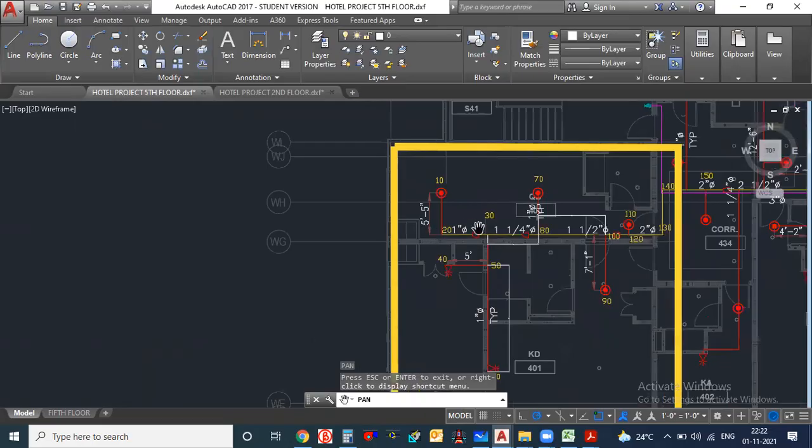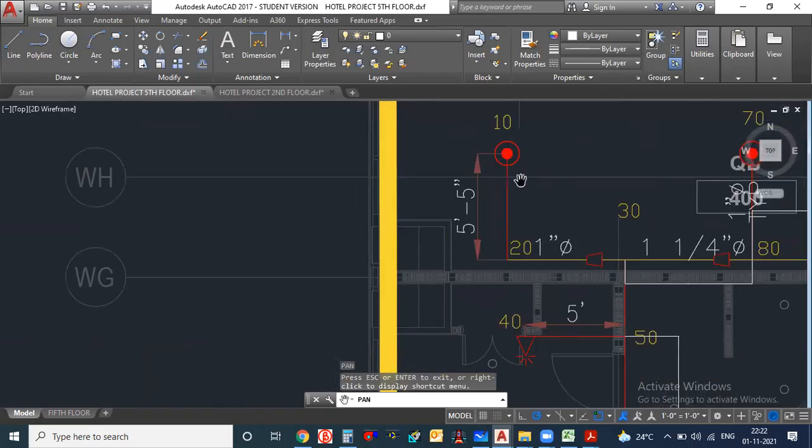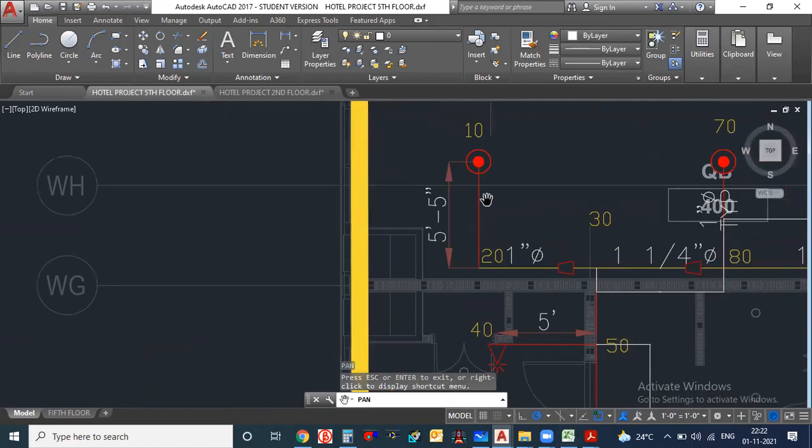So I have written here in the node number 30. Yeah, you consider the elbow at the 20, but there is another elbow at the 10, before you fix the sprinkler. Already written. Sir, no, he's asking for the upright. If you make it upward or downward, you will add one elbow here with the sprinkler, at the sprinkler itself, other than the corner. Under the sprinkler or above the sprinkler, there is an elbow. Why are you writing only one elbow? It should be two elbows between 10 and 20. You got my point? Yeah, I got your point.